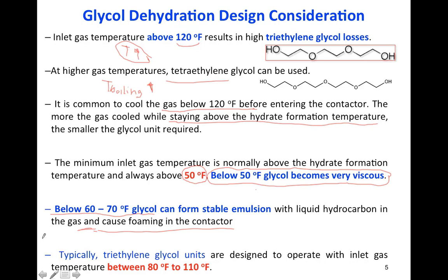For example, in case of using triethylene glycol, typically the inlet gas temperature is between 80 and 110, considering all the above mentioned points. So this slide is important. As you see, there is a lot of important information in this slide that you need to learn carefully.